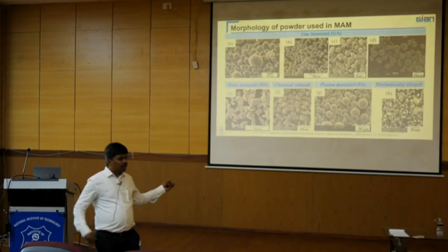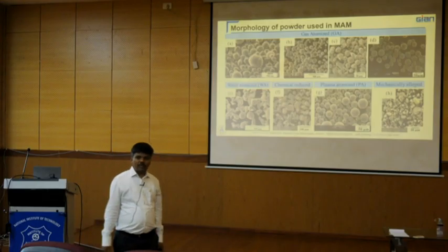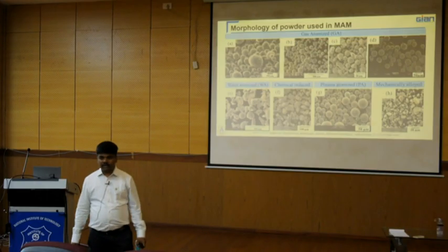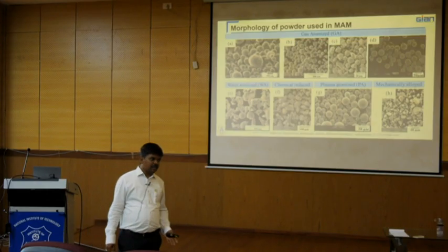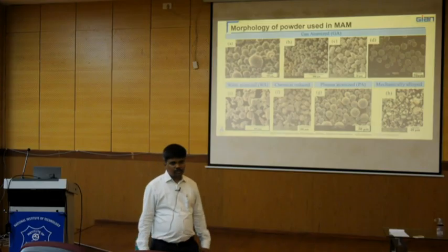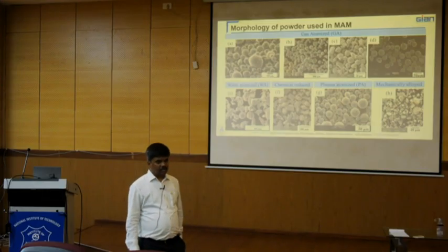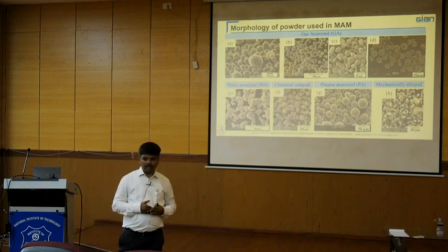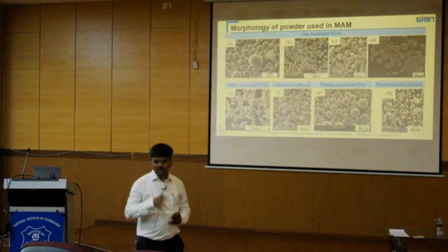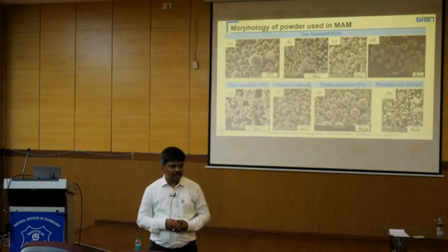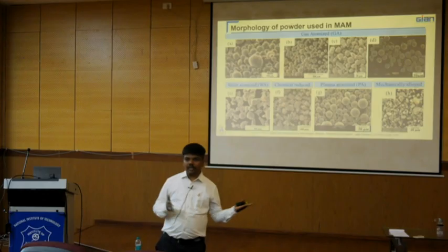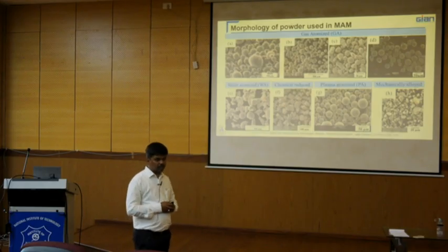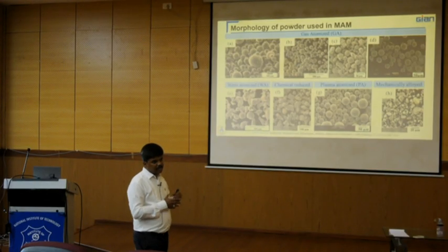For simple parts which are not highly required for aerospace applications, there is no need to worry about highly atomized powder particles. Yes, it will definitely be flowable, and it can also have good compaction ratios and packing factors. The packing factor mainly depends on the distribution of your powder particles. For the DED process we use 45 to 110 or 45 to 90, and for PBF we can use 5 to 45 or 15 to 45. That is the distribution of the powder particles we are using. Based on this distribution we get the packing factors.